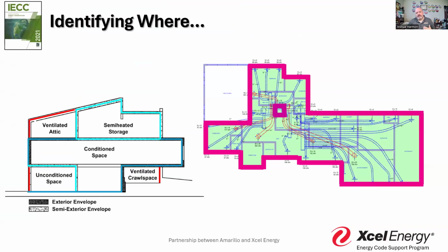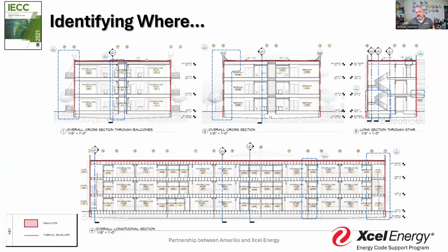So again, it's a question of identifying where it is. And like we talked about before, when we talk about multifamily structures or larger residential structures, remember the energy code separates out R2s, 3s, and 4s: rooming houses, dorms, hotels, motels, assisted living facilities that are 3 stories and less above grade fall under the residential provisions. Now, as we talked about when we talked about the air barriers, the code also kicks them back to commercial, but at the same time, it falls under the residential provisions.